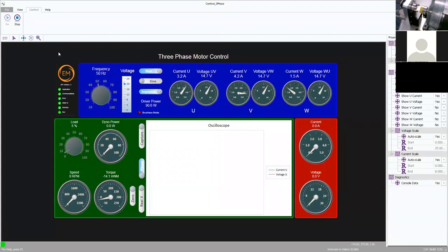So just to take you through this, basically, on the left-hand side here, there's a number of LEDs which are used to allow you to check your system's okay. So there's an LED to show that the application is running, one to show that the USB is connected, one to show that the machine is plugged into the cradle properly. The cradle has a couple of micro switches, and there'll be no output unless the cradle's pushed in.